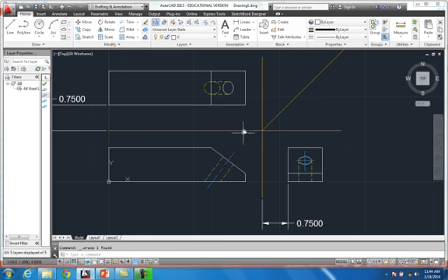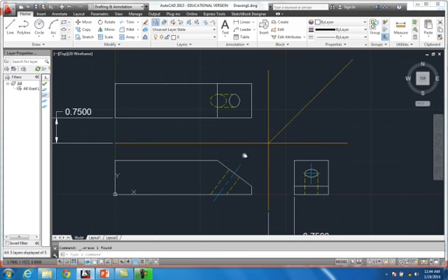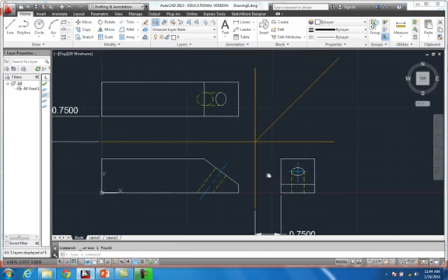it comes up at an angle, and looking at this, I can't see this plane at all. It's on an incline, right? And you see here's the true distance in the edge view, but I don't see the whole surface, the whole plane. This is foreshortened, and on my right side it's foreshortened. So I want an auxiliary view.